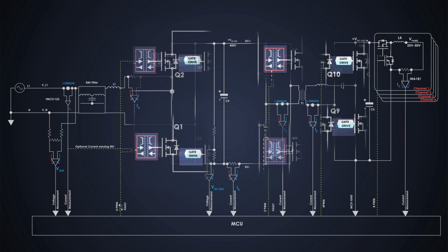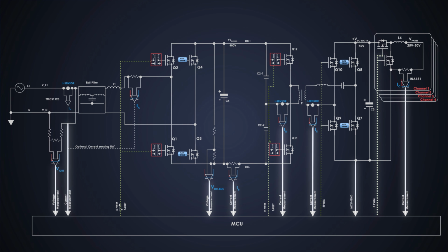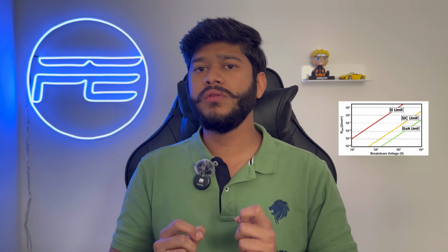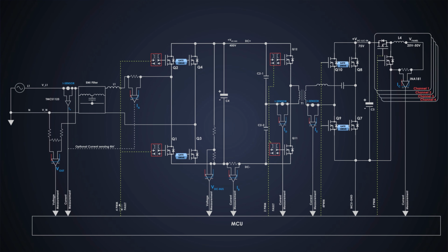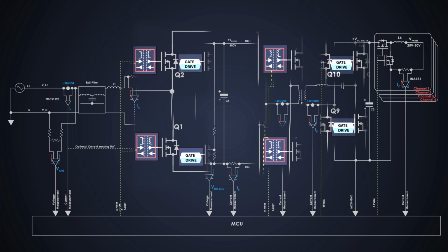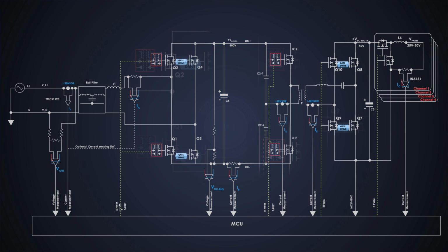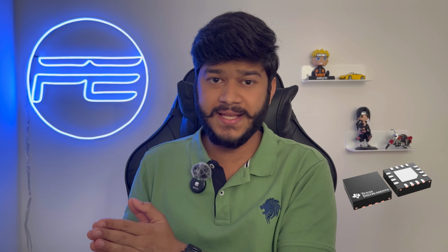To make sure that this circuit works efficiently, we have to select a good set of FETs with optimum performance. We have also seen many basic things about these transistors in older videos. If we really want to know how to make an efficient solar inverter, we should follow the latest technology trends. And not just FETs, we should select accurate gate driver circuits for these FETs as well, which will switch them very efficiently by producing minimal power losses. Well, it is a hard job, but there are a few application specific ICs which offer latest technology.